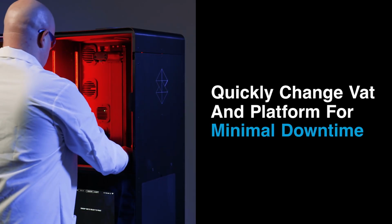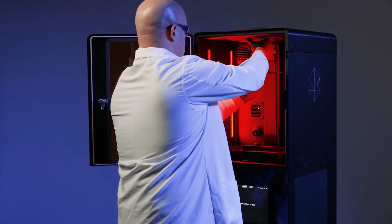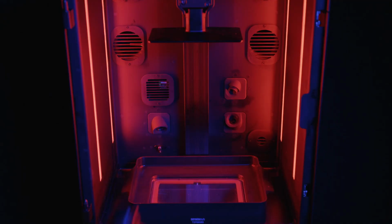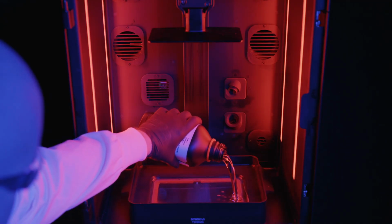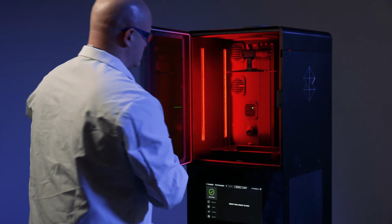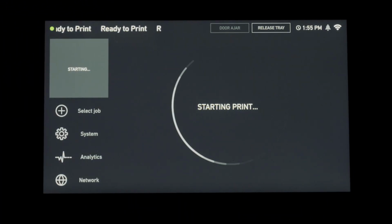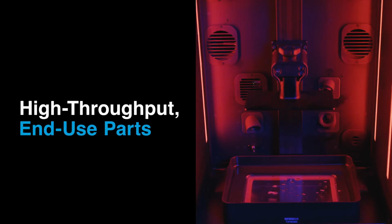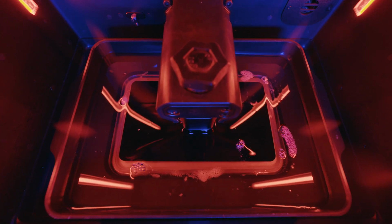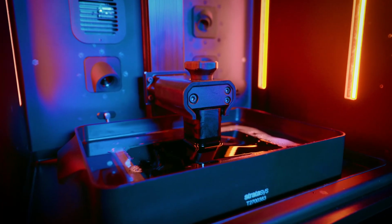Compared to a laser, it's faster, because the laser has to go point by point, and this can do the whole layer. It's also a stronger source of light compared to those home-based printers where you have an LCD display, because the LCD display will take some energy from that light, and not all the energy is transferred to the substrate.